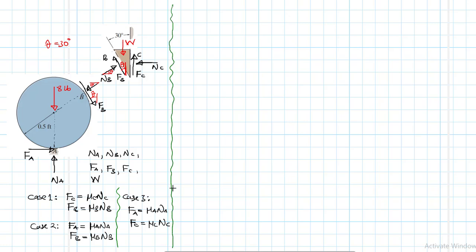So we'll try them once we also write down all the available equations of equilibrium. Then we'll be getting 2 equations from each case. Then we try them, calculate W, check the slip at the other point, and do the same for the rest, and then pick out the largest W. Right. So then let's write down quickly the equations of equilibrium. All right, there we go.